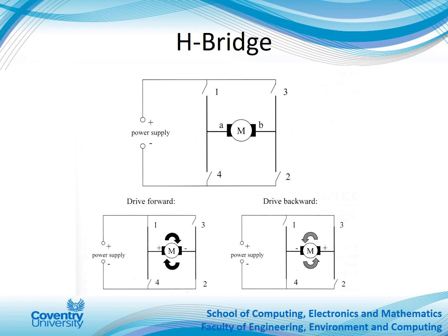The way to implement an H-bridge when using a microcontroller is to use a power amplifier chip in combination with the digital output pins of the controller, or add an additional latch. This is required because the digital outputs from a microcontroller have very severe output power restrictions. They can only be used to drive other logic chips and never a motor directly. Since a motor can draw a lot of power, for example over 1 amp, connecting the digital outputs directly to a motor can destroy and blow up your microcontroller. A typical power amplifier chip containing two separate amplifiers would be an L293D from SGS Thomson.